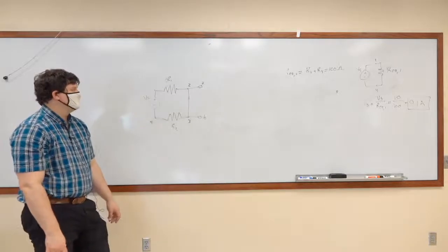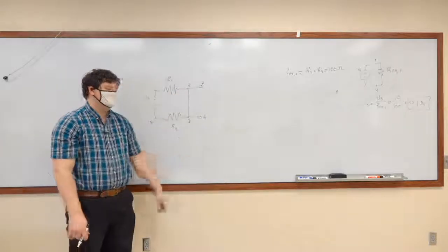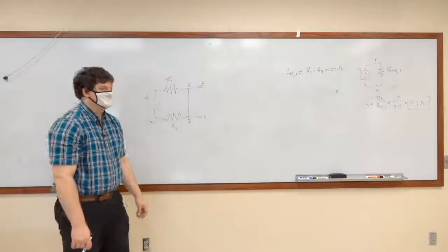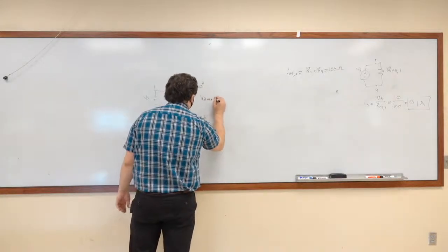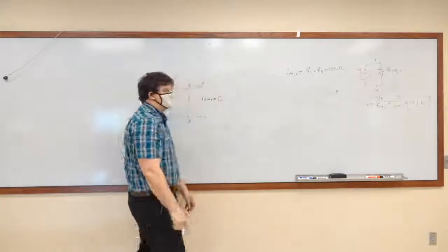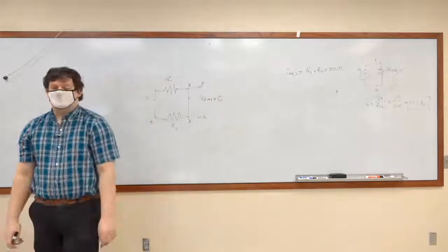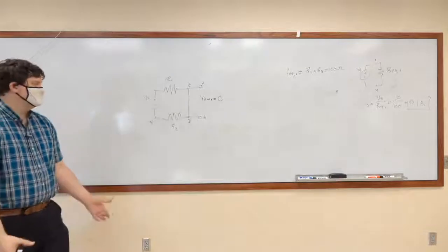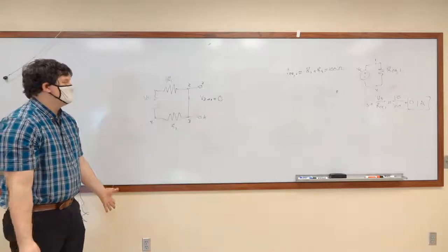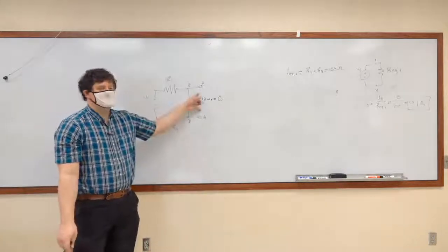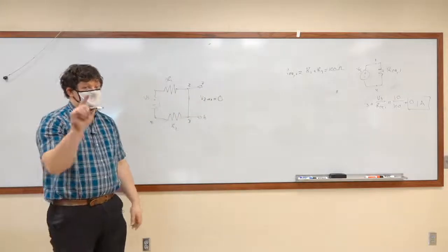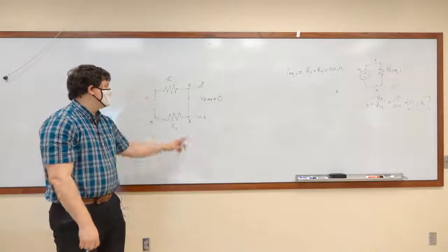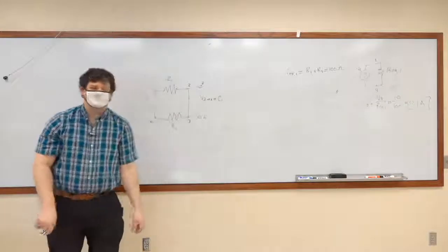What is the voltage between 2 nodes that are connected with a short? It's 0. So here, VA to B is equal to 0, and we know that, which means our Thevenin equivalent resistance equation for this, unfortunately, you can plug in any component here, you will never get power out, because it's already shorted. So that is something that you have to consider when you're doing these equations.